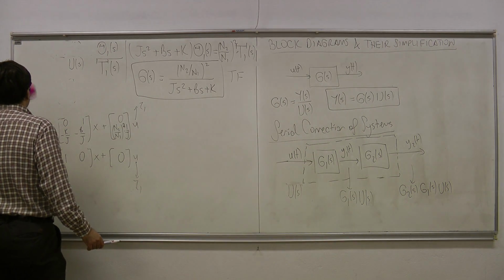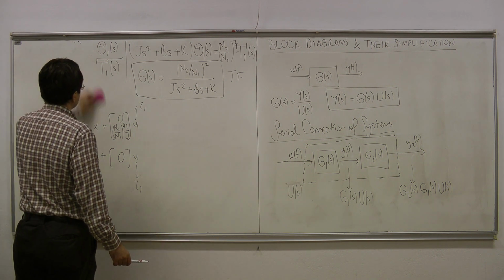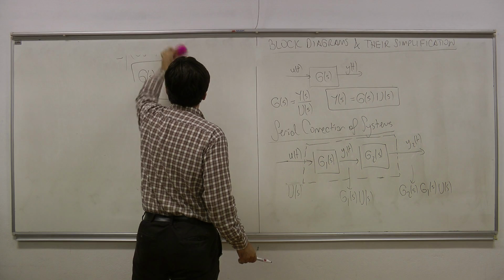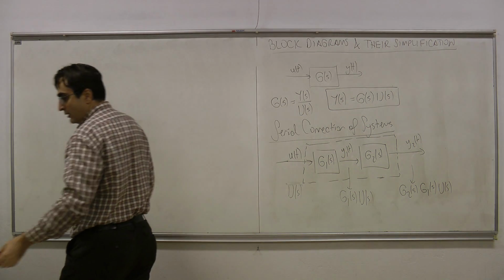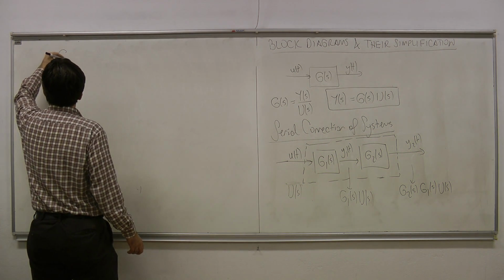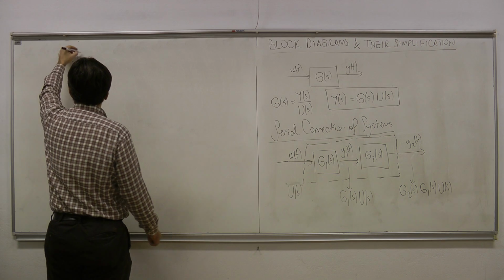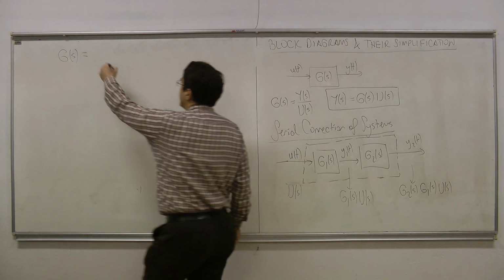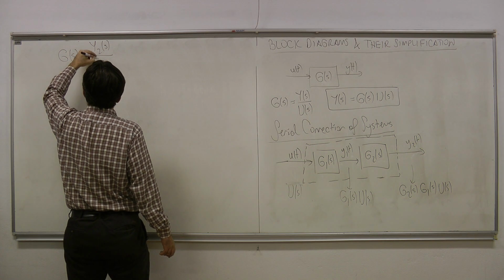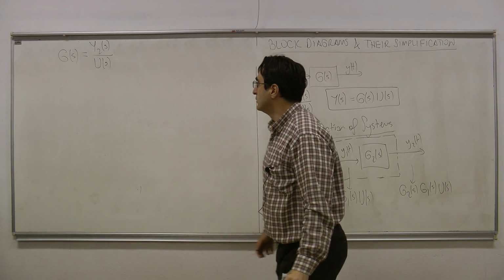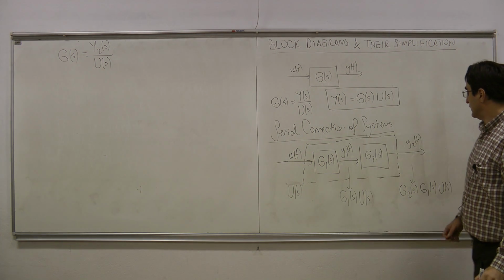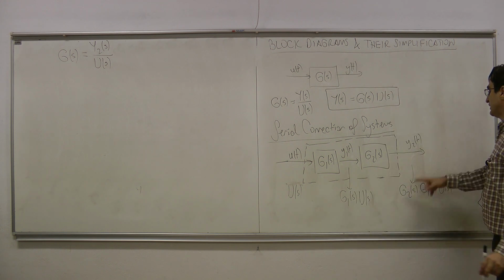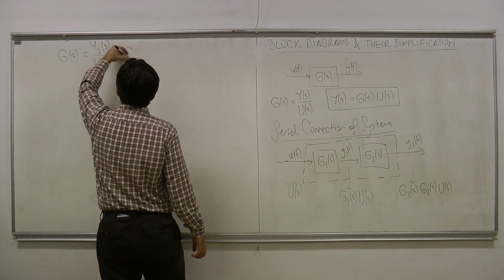So then what can you say for the overall transfer function of the overall system, this connection? What is this overall connection equivalent to in terms of the transfer function? We are going to obtain the overall system. It is going to be the equivalent transfer function of the system. We know that the transfer function from u to y2 is going to be the Laplace transform of the output divided by the Laplace transform of the input. Okay? What do you think this ratio is in this case? This is y2 of s given like this, and if I take that ratio, this is going to give me the multiplication of g1 of s times g2 of s.